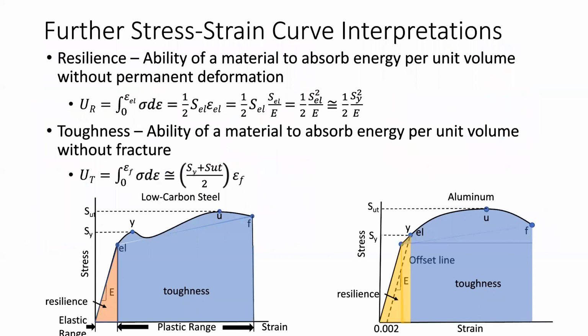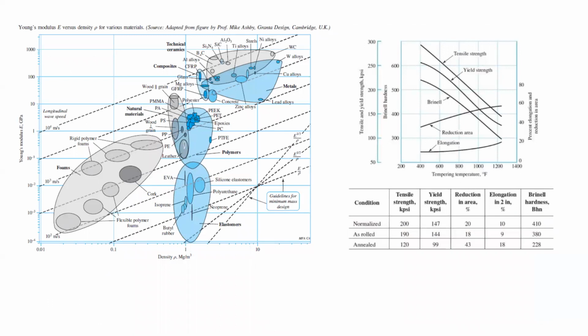Something else you can do is take advantage of the fact that metals are still ductile after the yield point. So if I were to make ceramic control arms and they somehow broke because I did my calculations wrong, my car would just, I don't know, fall on the ground and like it could injure someone, right? Whereas if you use a metallic part, after the part yields, you can detect it. The deformation is usually pretty obvious, but it isn't a critical failure. So this is another kind of hidden reason why metals are preferable to something like ceramics, even though this plot seems to imply that you would always want ceramics. So it's always important to recognize like the interplay between all these different parameters. So I think this plot kind of makes a generalized way of how these different parameters interact in metals.